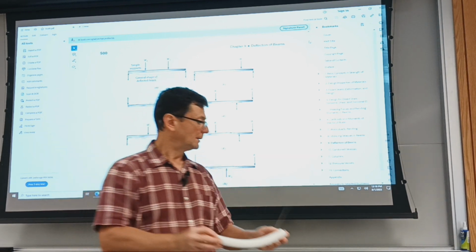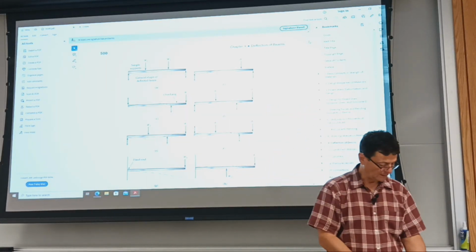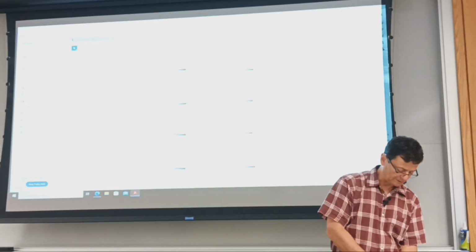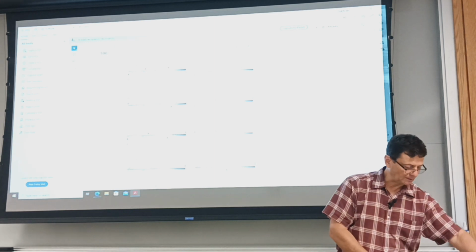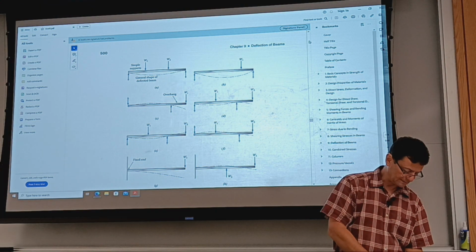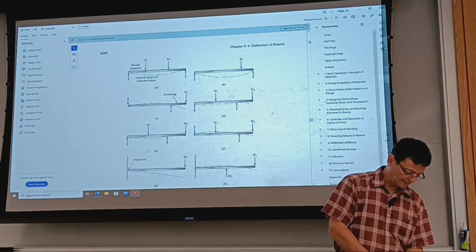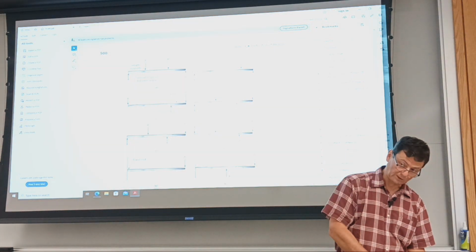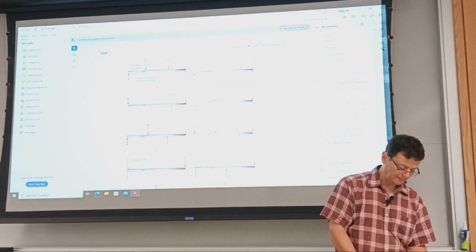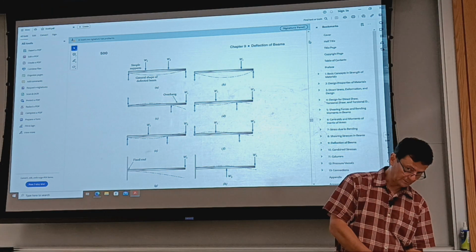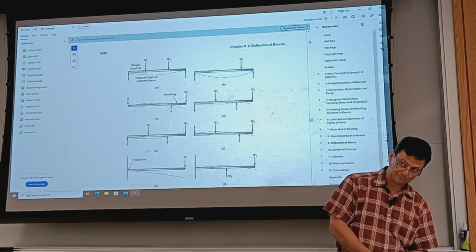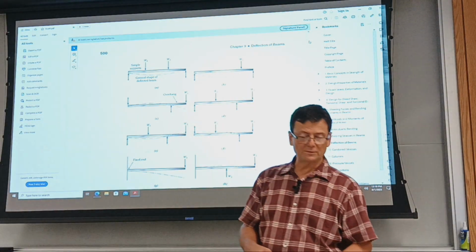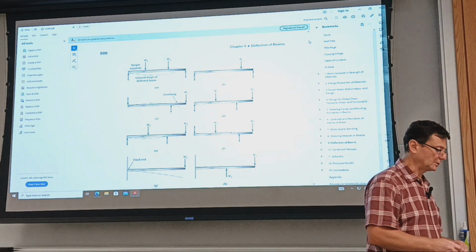So I'm trying to do a one person show, this being the tangent, you can see, so I'm moving it, sliding along. I slide it along, so it's tangent. It's a smooth curve of the beam, and I slide along, and you can see here it's horizontal, remains parallel to the original axis of the beam, but then elsewhere it goes from, as you look at my contraption here, you see a negative slope, and then you see a positive slope, okay? And those are likewise or could be important.